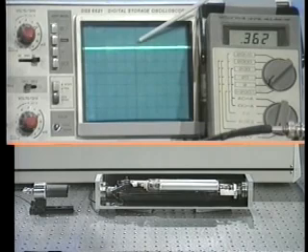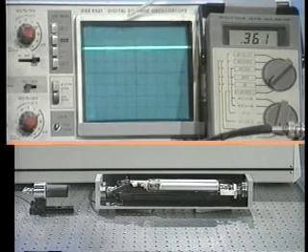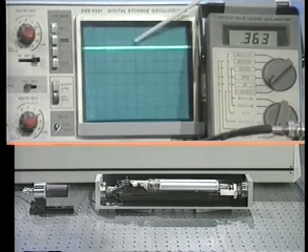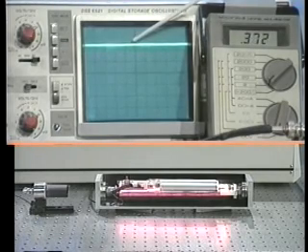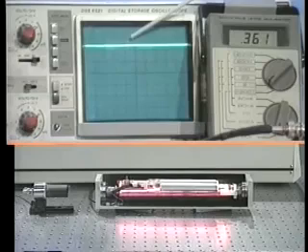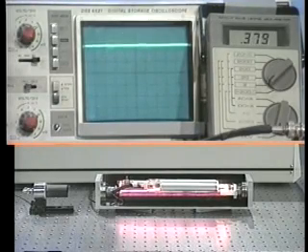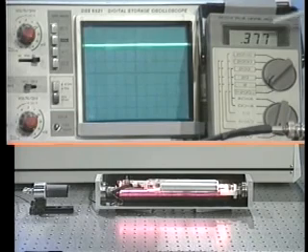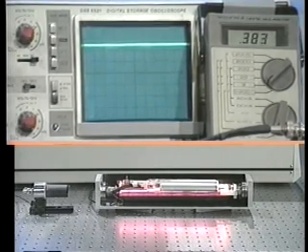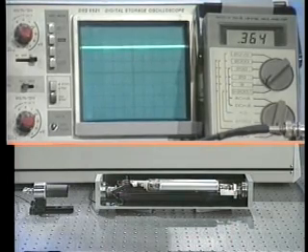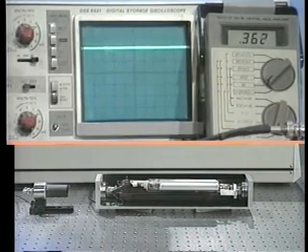Again, you can see on the scope it went down. In fact, just watch the scope for a little while. I'm going to turn it on and off very fast so that you get a feel that here it goes up a little bit and down a little bit. Since it's only a few percent, it's difficult to see it on the scope the way I have it set up, but it's much easier to see it on the meter. So you can see that with amplification we have 380 something. With no amplification, then we're back to 360 something. Again, roughly it's about 5% amplification.